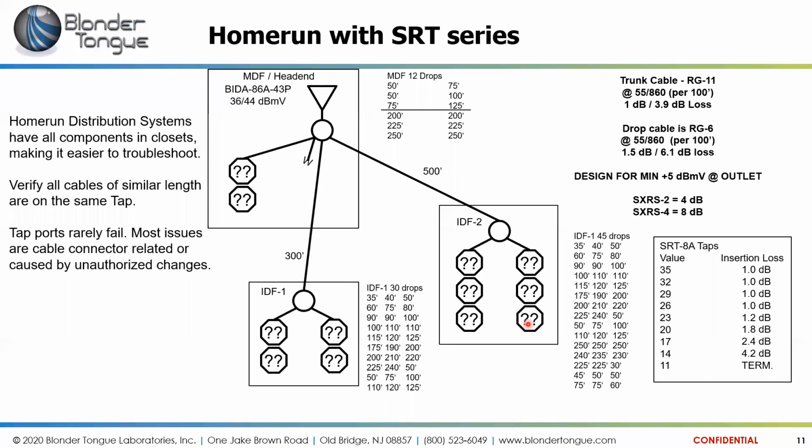Is there a specific torque for terminators in inch pounds? Yes, there is. We typically use 20 inch pounds. You can search, I know several of our distributors do sell cable television torque wrenches.